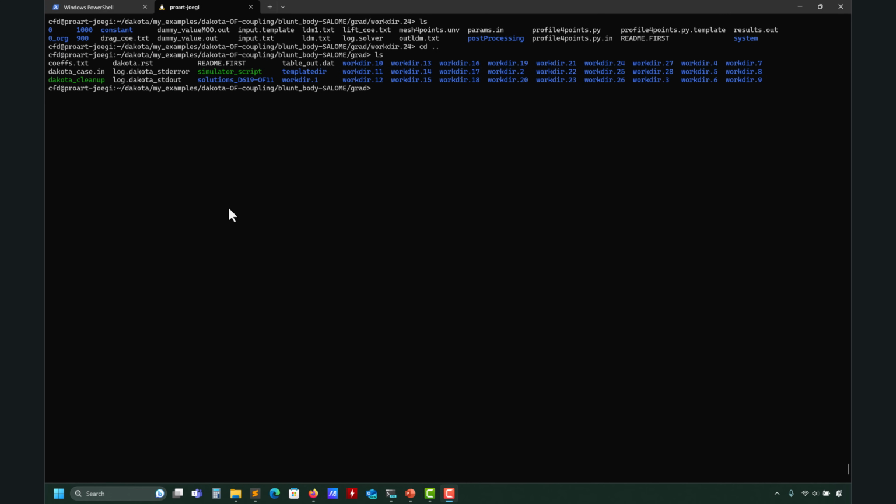Okay, by the way, I forgot to mention something. Remember that if you have a case here, you have all the folders. If you want to run another case, remember to clean up these directories. You have all this data, and likely Dakota is going to give you problems, so you need to clean up. And here you have this automatic script that is cleaning up everything. It's going to clean all the trays that you have, but also these tables out, restart files, and so on. So if you type in your terminal, let me show you here, you have dakota clean out.